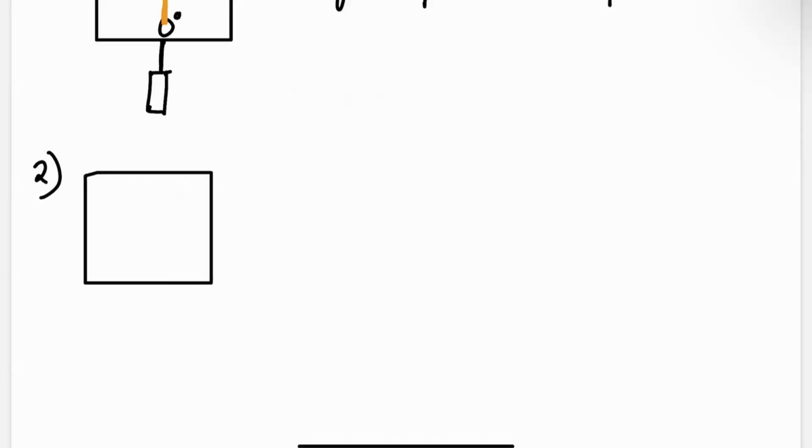Okay, so once again, I take a patch. Let's say I use a rectangular patch, or just a general patch, right? So we'll say this is L and this is W. But now I feed the patch on the diagonal. Okay. So let's say I'm using a coax feed in this case, it's on the diagonal. So then I'm exciting both modes now, right? Because you really excite this current, which can be decomposed into the V current and the H current, right? Okay, now both currents are excited.